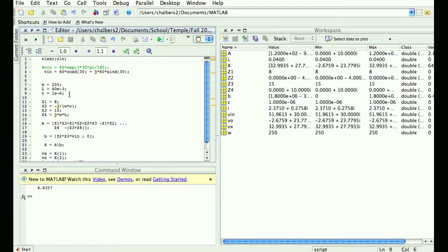Okay, so I'm going to change it from 1 microfarad to 10 microfarads. Got closer. Let's go up to 100. Ooh, now it's really close. Okay, so just to repeat what I just said, the first thing I even had to establish was what direction to go with the capacitance. Do I need to make the capacitance bigger or smaller? I multiplied it by 10, and I saw my phase angle got bigger. Multiplied it by 10 again. It got bigger yet. Okay, should I multiply it by 10 again?